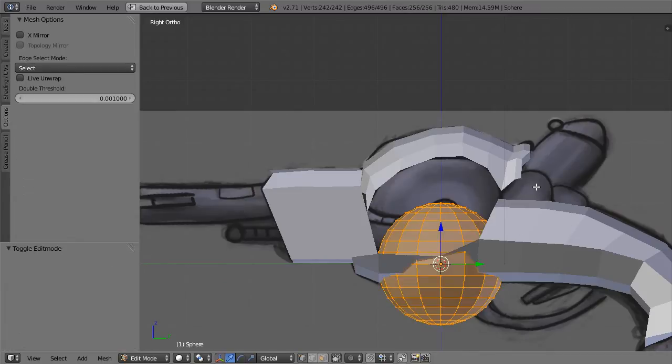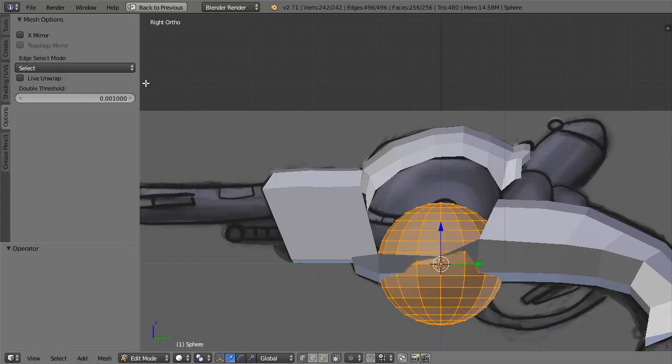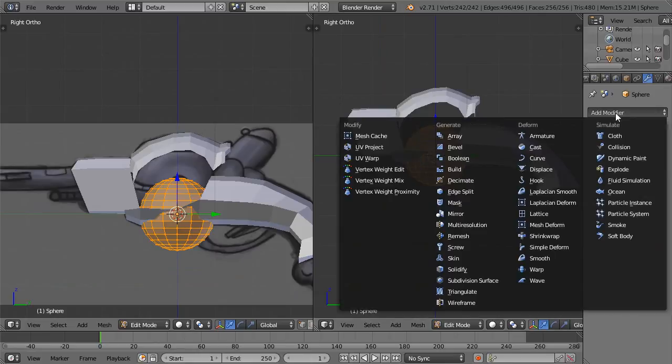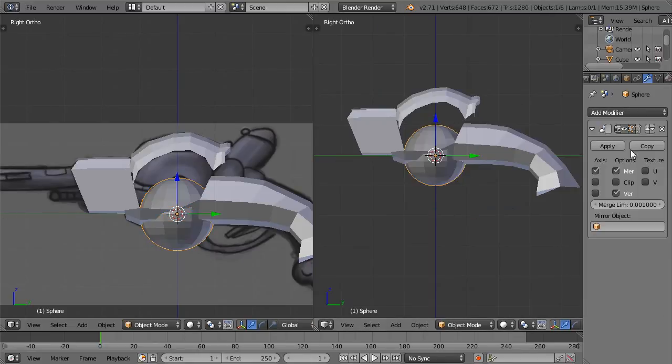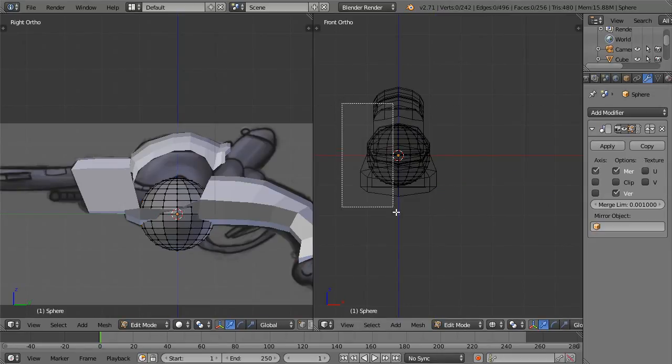I'm going to hit Edit, Rotate. Actually, before I do that, I'm going to close down this view, bring up the modifier stack, and I can't do it because I'm in edit mode. Switch, turn mirror on, flip it on the side, and I'm going to select half the mesh. And because I know that I don't want that, I want everything but half the mesh, I'm going to hold down Control and hit Delete on my numpad.